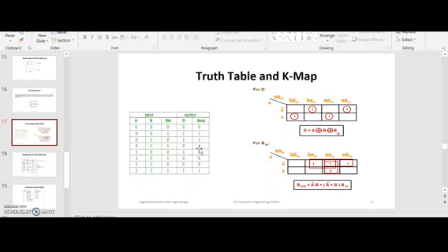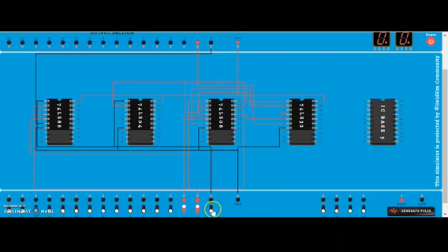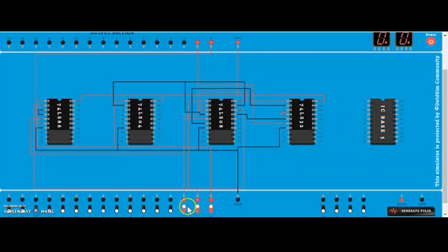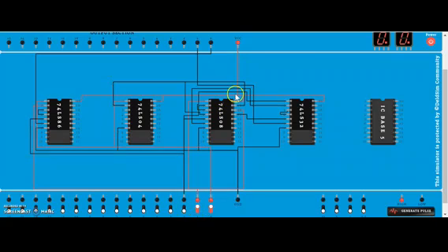Yes. Now we will see 1, 1, 0. So A minus B, 1 minus 1 will be 0, and there is no borrow. So we will check it, this 1, 1, 0 now. See, no borrow and no difference is there. So this is how the full subtractor works.